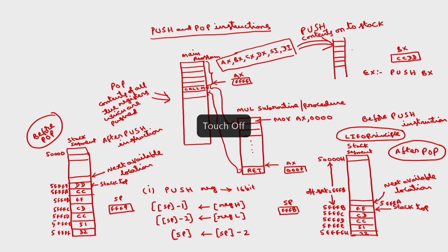While the microprocessor is executing these programs, at this point AX is this, the status of the various flags, say carry flag is set, direction flag is reset, some status is there. Whereas here if I use some other arithmetic logical operations, this carry flag status may change. At the end of this, the carry flag status may be changed to 0, direction flag may be changed to 1. So if I return back here, what happens?